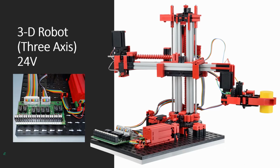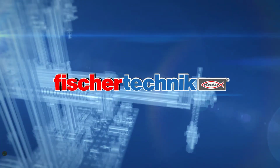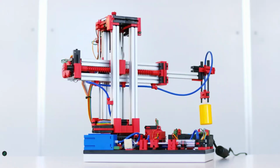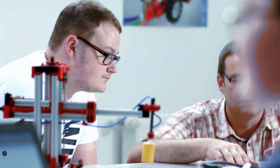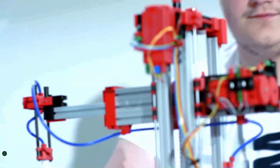Now, the next up is going to be the vacuum gripper robot, which you see here. And starting here, we get to show you what the model looks like in action. So what you're about to see here is the vacuum gripper, which is a 3-axis robotic model with a vacuum gripping device attached to it. The model is designed to precisely pick up and position workpieces in 3-dimensional space. Now, this model includes 3 encoder motors, 3 push-button limit switches. It has a vacuum suction device, a compressor, and a solenoid valve. The dimensions for the model are approximately 9 by 19 by 15 inches. It has a weight of just about 7 pounds.